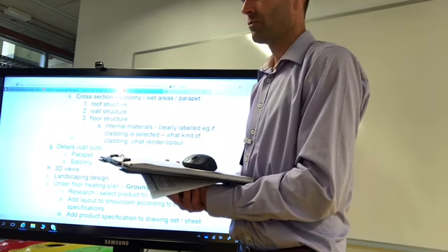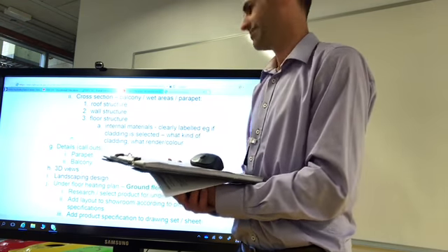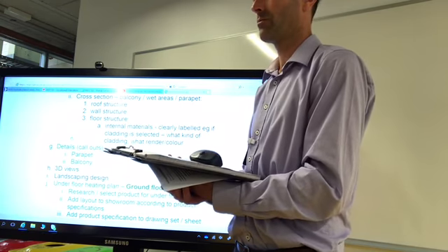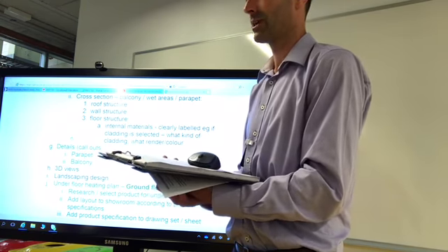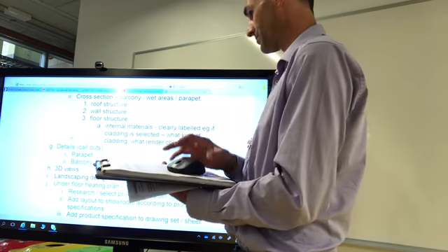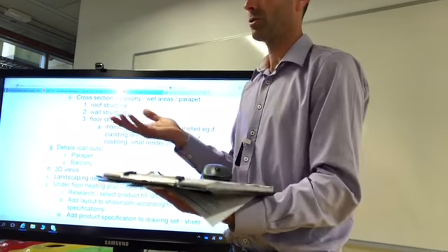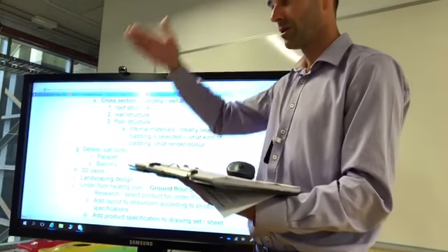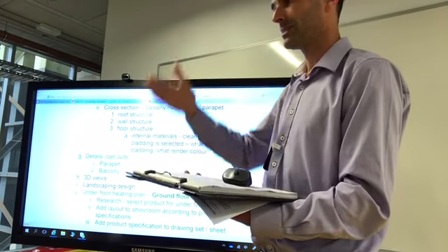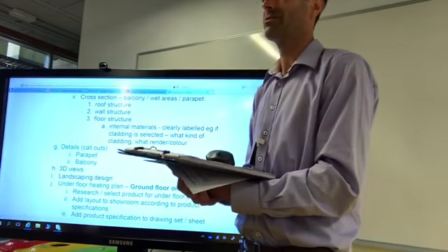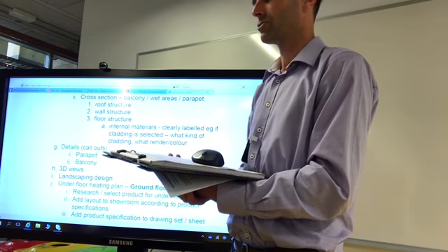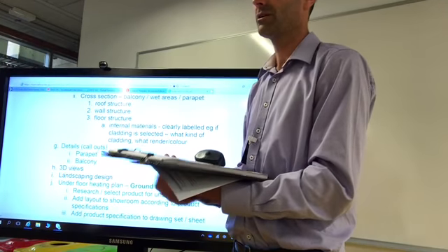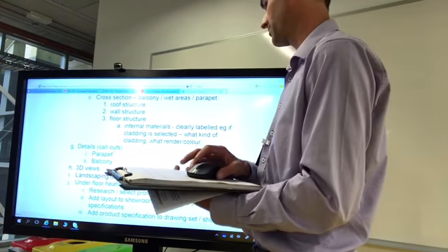With what your roof choice is, that's going to influence how your parapet detail comes together. Whether you've got your flat concrete roof and your EPDM membrane carried up onto that parapet, essentially that's going to be the less time consuming detail to draw of those options, whereas if you were to go to your box gutter, well, it's going to be a little bit more detailed with that.